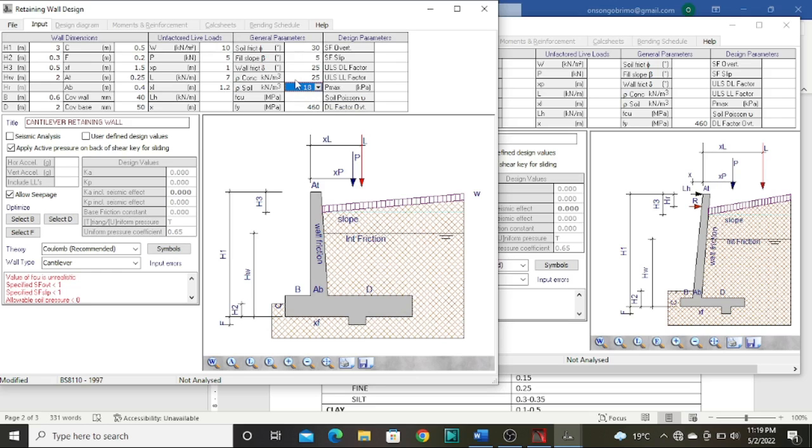But also, from a geotechnical report, kindly determine the density of your soil. FCU is normally the class of concrete you're designing for, and from the British standard, we could choose class 16/20, that is class 20, or we could use class 20/25, which is class 25. So in this case, let's assume 25.